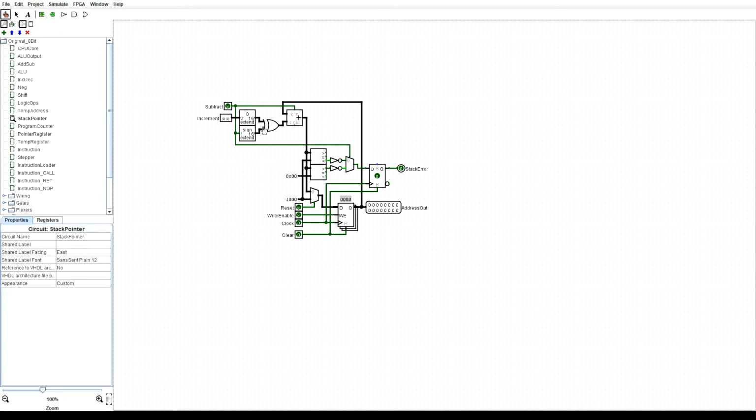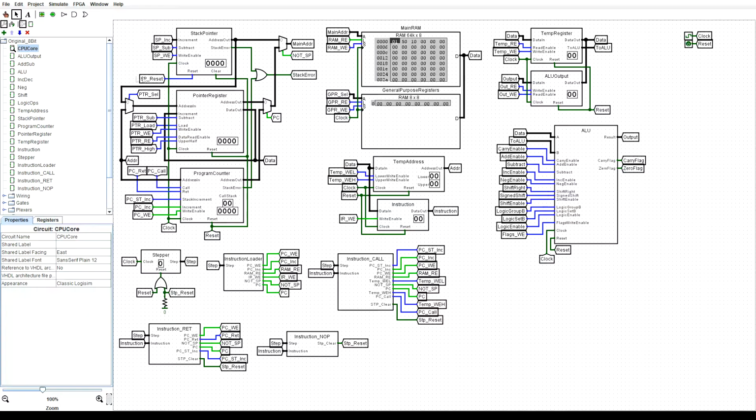Oh, and we have to do something special to initialize the stack. So if we were to do this, we can set this here, write enable, so the reset and write enable will put the 4096 into this register. We clock that, and that's the complete initialization of the stack. We set this high and set this high to initialize the stack, and I have an instruction in the instruction set, if you go back and pause the video, for doing exactly this.